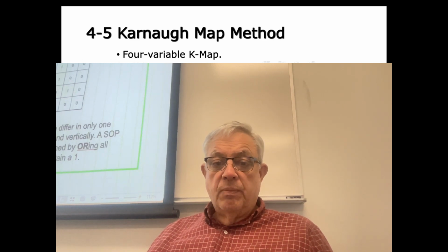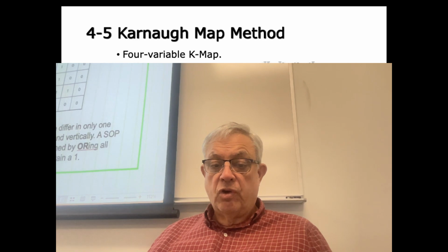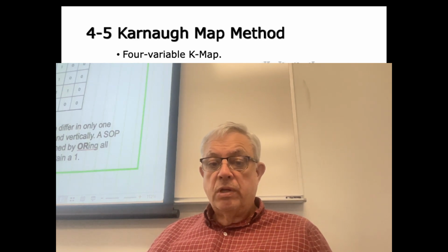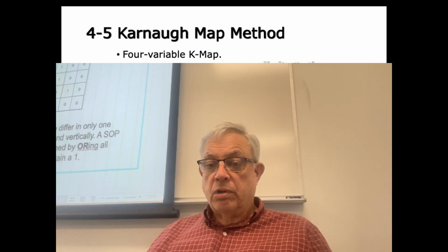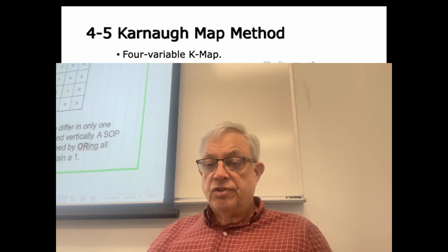So now I take a much more extended expression. I've got 4 inputs to this Karnaugh map, and I can see that I've got an output of a 1 when A, B, and C are 0s, but D is 1. So I come over and I find that spot. A and B are both 0s, C's a 0, and D's a 1.